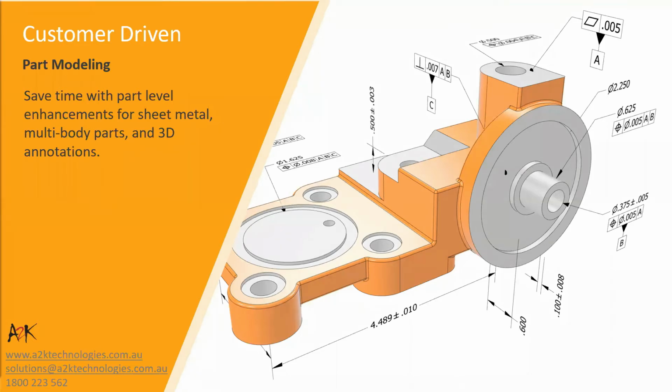The unwrap command has been given additional options for constraining planar holes and alignment of the unwrapped surface. Sheet metal flange angles can now refer to existing edges and faces for the specified angle, no more formulas or equations to maintain that associativity. And iProperties can now be referenced into 3D leader annotations and general notes.